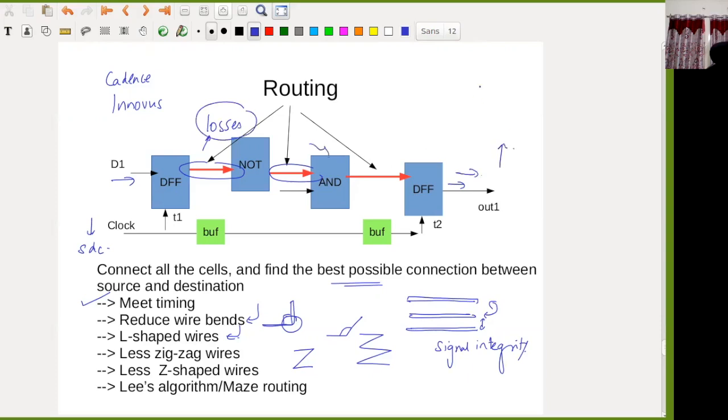But at the destination or at the receiver, you usually have certain specifications to meet. So for example, if you sent a 1.2 volt signal, you don't really expect the same here. So you would probably have a different set of specifications here to identify it as a high and a low. So you have to meet that specification. That's also technology dependent. It's also dependent on the interface.